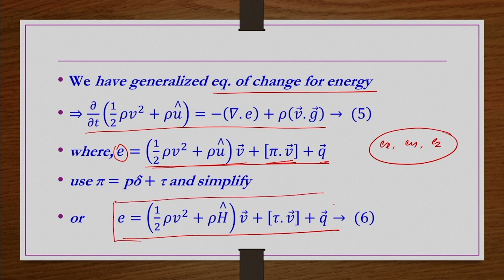So, this we are going to simplify for the given problem, because we cannot directly write the energy equation in the temperature form. Why can we not write it? Because in that form, the viscous dissipation term, for power law fluids, may be different; for non-Newtonian fluids it is incorporated in a different way. How different, we can understand from here only, because this term is going to play the leading role now because of the non-Newtonian rheology, and this is not directly available in the energy equation in the temperature form. So, the same equation is written here also.